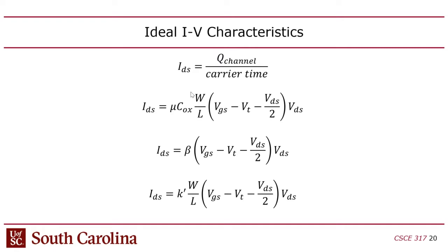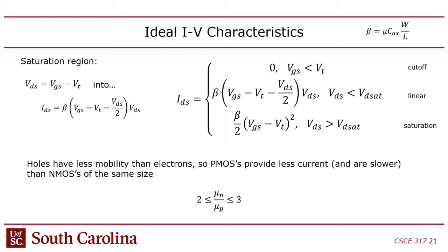Of course, the problem is that when the transistors saturate, they're limited in how much current they can pass, and ultimately the most current you can pass through depends on the width, the size. It also depends on the gate voltage, though, as we'll get to.